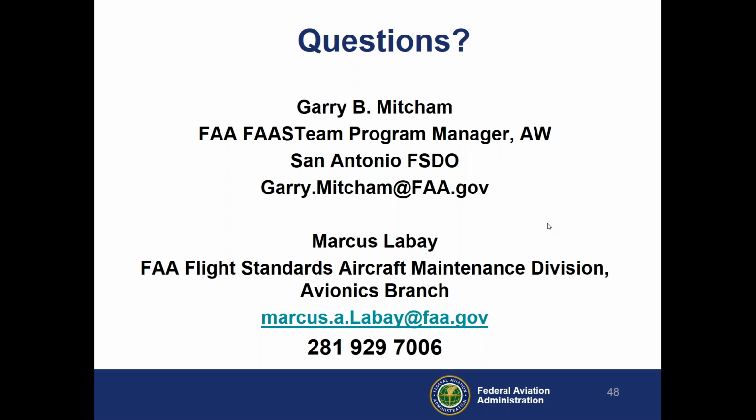Sure. Just so everybody's aware, the ATC automation platforms, in other words, what controllers will see on their displays, on their data tag, when it comes to ADS-B source information, the barometric altitude being broadcast by the aircraft under test, or the ADS-B system under test, while that aircraft is in airborne mode, is what gets through to the ATC displays or other ADS-B In or traffic-equipped aircraft.